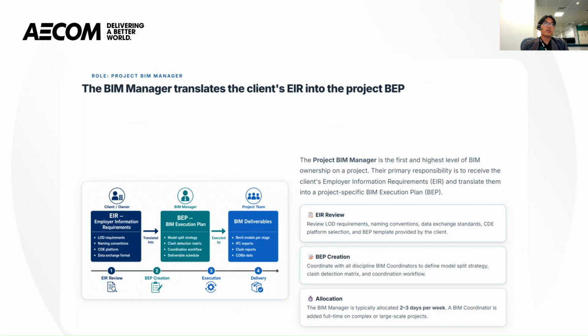The BIM manager is simply the person who manages the requirements from the client, the EIR, the requirements from the client employer, and translates that into a BIM Execution Plan, the BEP, trying to answer the questions from the client. And with us, we have the idea of what the BIM deliverables are, the MIDP, the list of items that we have to deliver.